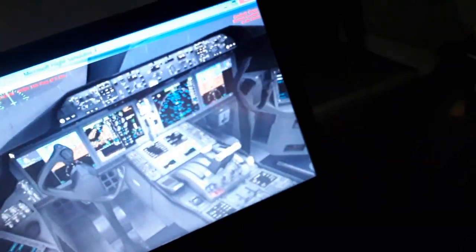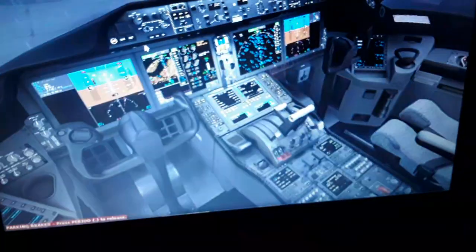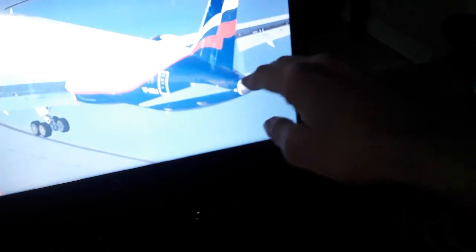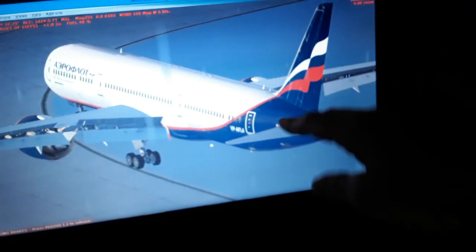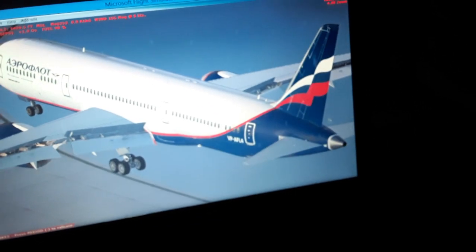I'm going to show you the flight controls in a little more detail now. So you need the horizontal trim stabilizer. I have it here, this switch. So this is what it's doing. As we fly, we can climb and descend using the elevator, and we can trim it the same way, the elevator to move up or move down, or the stabilizer, so it will balance the aircraft in flight and control the aerodynamic forces.